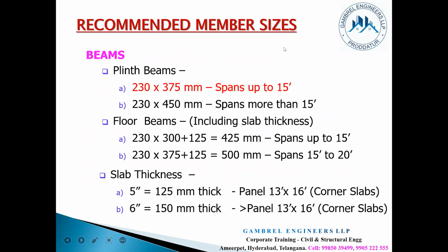Plinth beam size also. Now column size is over. Next, focus on the beam sizes. How to choose the beam size? If it is a plinth beam, the plinth beam obviously will take only wall loads and doesn't take any kind of slab load.